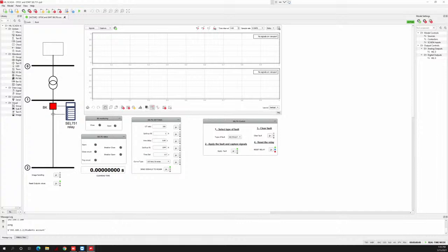And if there is a short circuit, this relay must identify the situation, send the signal to the circuit breaker, and open, okay? I think the first simulation that Marta will do is just send the signals without any fault to the relay. And you will stop over there because I will show them that there is real current coming here, okay? Once you have the model here,